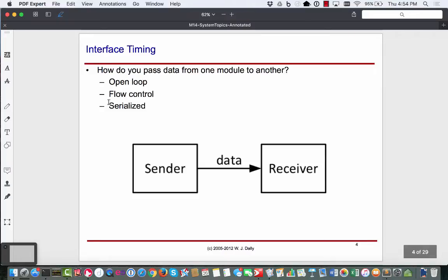So one challenge that we face often is how do we pass information from one digital system to another digital system. Within a chip, the output of one module goes to the next module, and we have those setup and hold time requirements, and we are done with it. But oftentimes these chips need to interact with the outside world, and the outside world may not be operating on the same clock cycle. In fact, it may be on a totally asynchronous clock cycle. And we saw that it does present challenges of not being able to meet setup and hold times, but there is also the challenge of how do we get the data out?